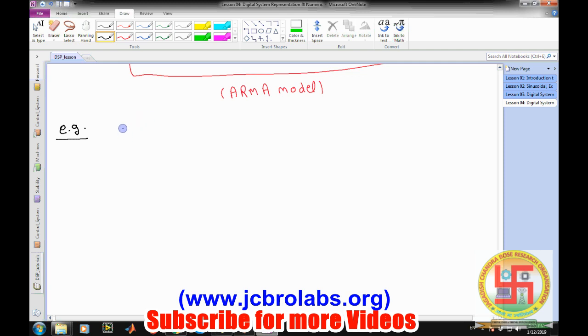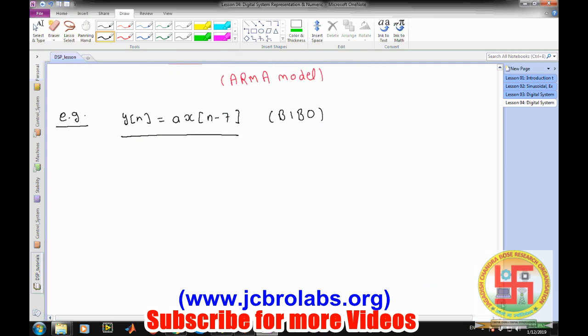Okay, so let's say we have an example, say y of n is given by a times x of n minus 7. The question is to find whether it is stable or not, or you have to find the BIBO stability of the system, whether this system is BIBO stable or not. So from our previous class, we know our system will be BIBO stable if the mod of h of n is absolutely summable. That means it is less than infinity for a bounded input signal.